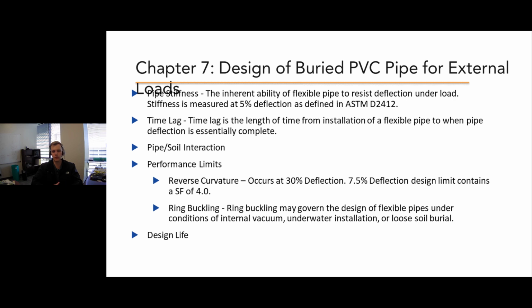Time lag, which is that length of time from installation of a pipe to when the pipe deflection is essentially complete, so when your settlement is functionally completed. It also gets more into the pipe-soil interaction and the varying ways to calculate that, as well as performance limits. Some of the big ones for PVC.